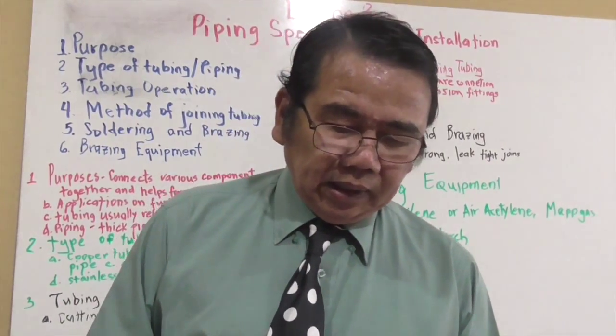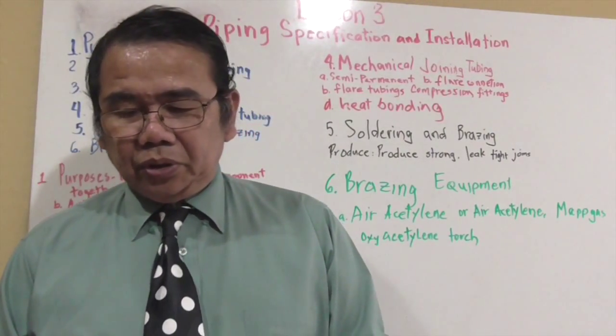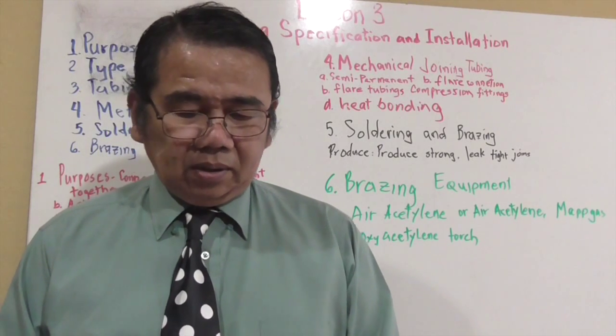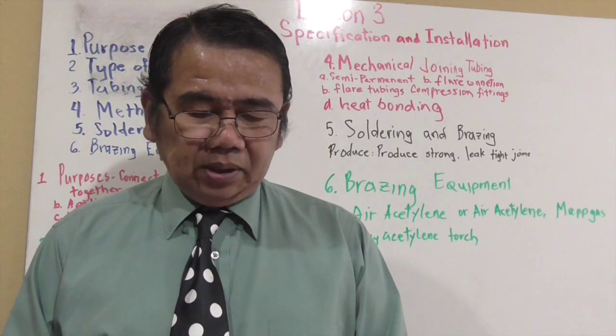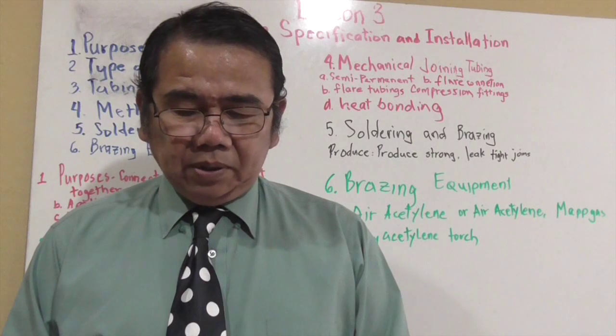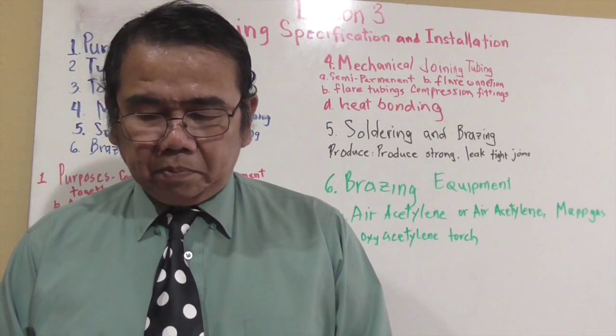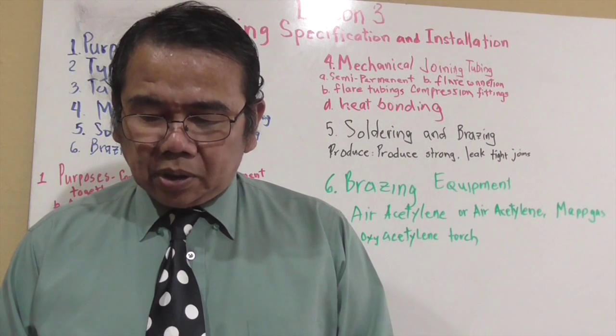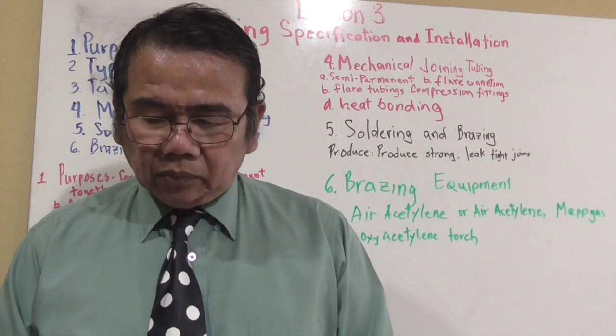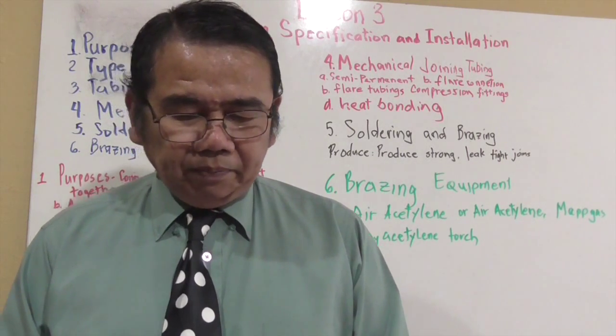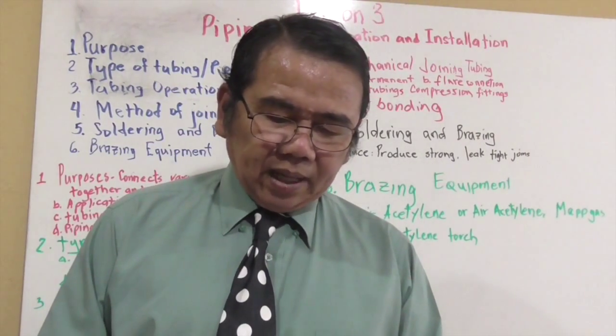Heating and blowing low temperature silver solder. This is another type. For silver soldering, a soft, bushy oxyacetylene flame provides the best type of heat.